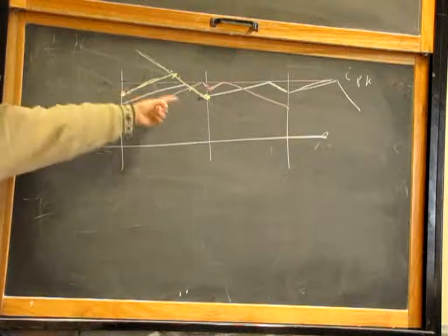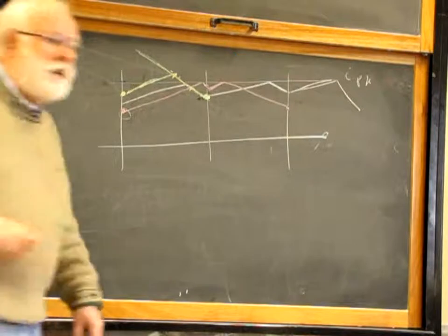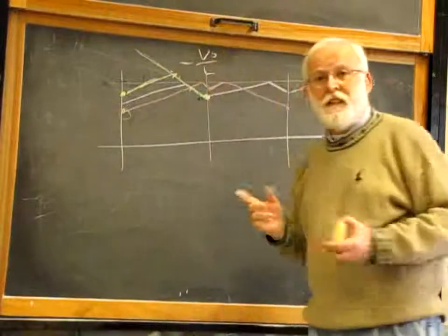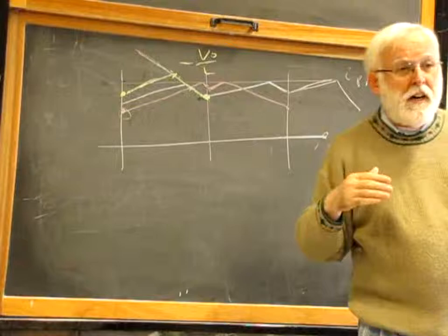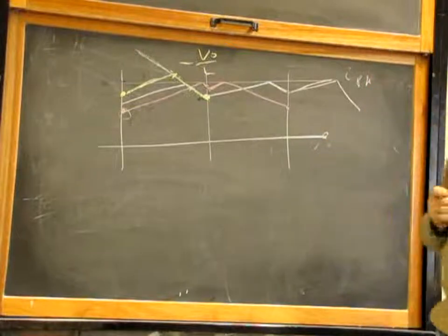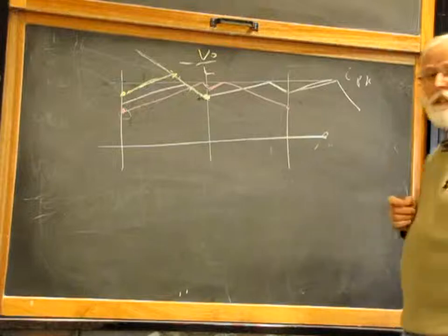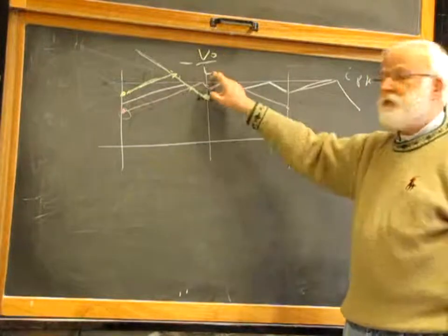That means what is this slope? Negative V over L over F. That's it. It's twice as much as the ramp that cancels the average error with respect to the peak average. So if you want to kill the subharmonic instability in very few cycles, in one cycle, theoretically, just use this